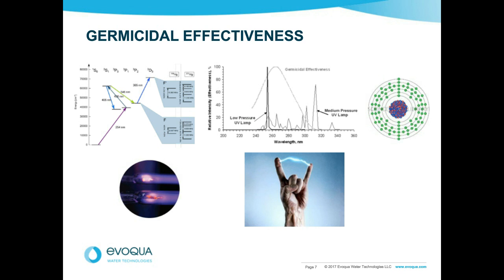So we have an AOP system. We use an electrode inside the reactor. Many people use hydrogen peroxide and UV, but peroxide has a fundamental flaw because it doesn't absorb UV very well. So the conventional AOP systems are very inefficient. Most of the peroxide goes straight through the UV system.